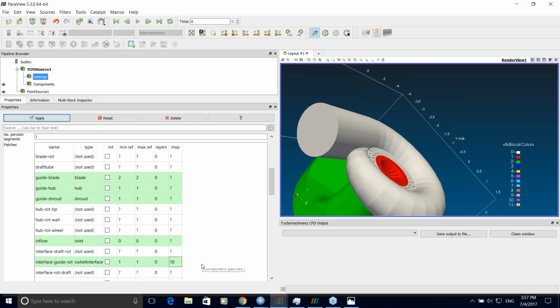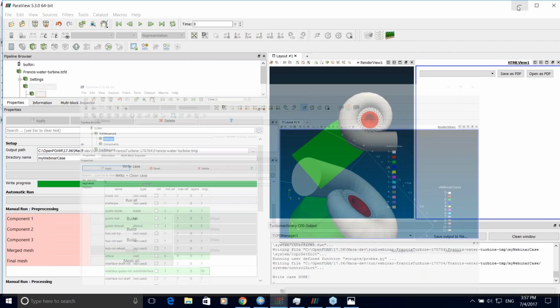It splits the interface into several rings or strips, and some averaging is done to communicate between them. Both approaches are provided for steady state, while for the transient there is only the AMI approach, because the rotor part is really rotating. I hope I answered your question.